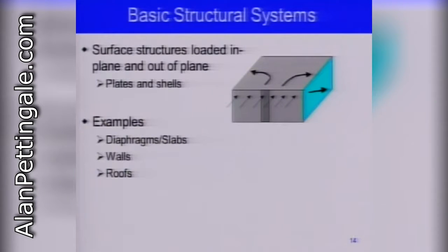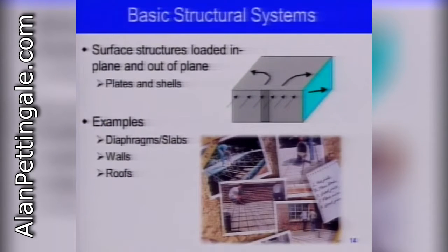And for the other wall, the load of the wind will be an in-plane load. So that wall would be loaded inside its plane. It would deform along its two big dimensions. However, with the wall loaded out of plane, you will see that it tends to tilt, and it's along its weak axis. So we really have to be careful about this type of wall. And then you can see that masonry can even be used for diaphragms, and that's how structures in the past used to be built.